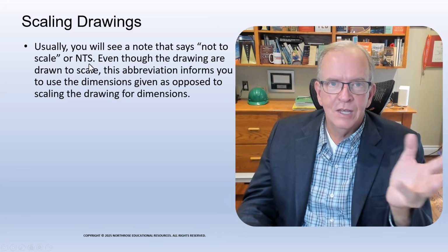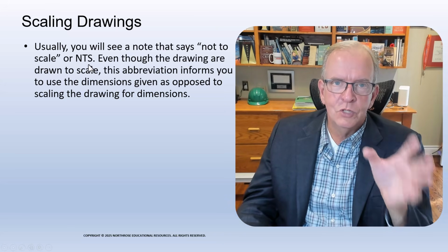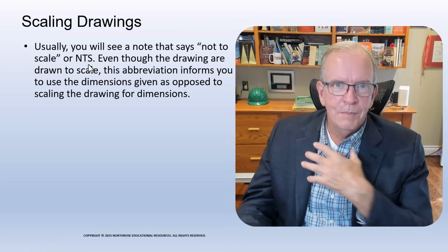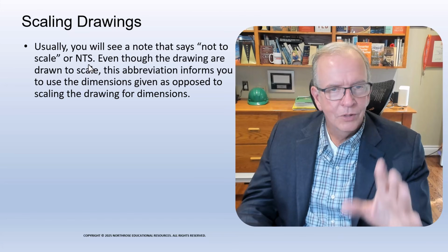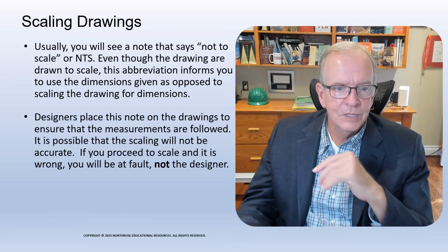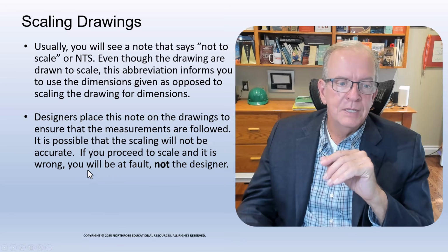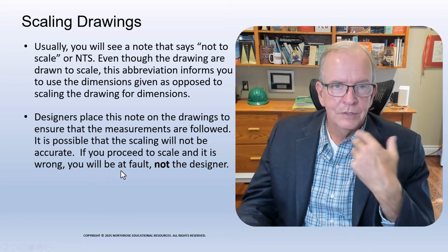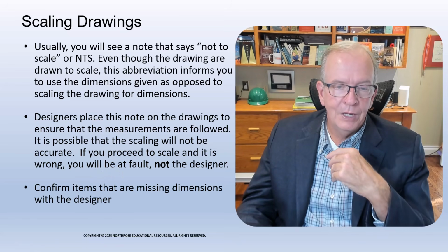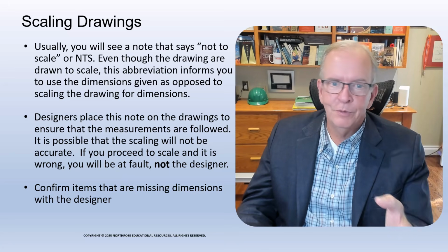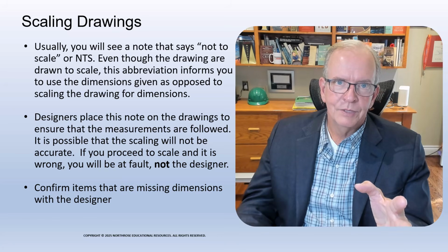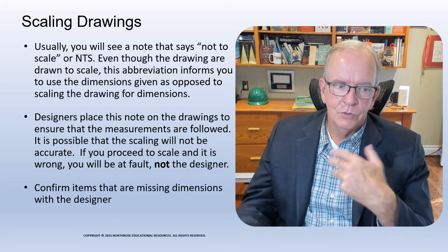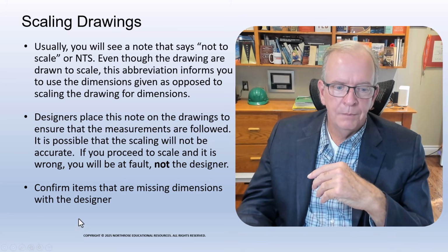NTS means not to scale. It's a standard. Designers don't want to be responsible that you've scaled something. They're saying that's on you. You find out from us if there is something missing. So it won't be their fault. It's not their fault, right? Even if they were neglectful at not putting a measurement, or even if something was out of alignment, you should ask, right? You should ask. So the onus is on you from that particular aspect.